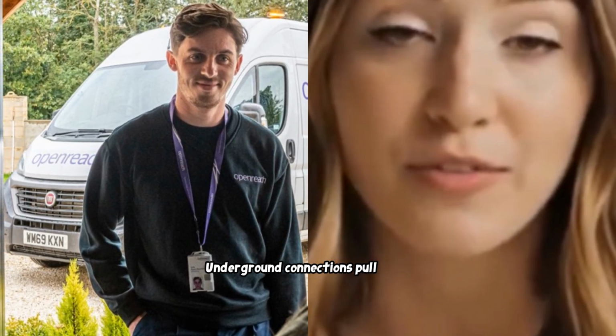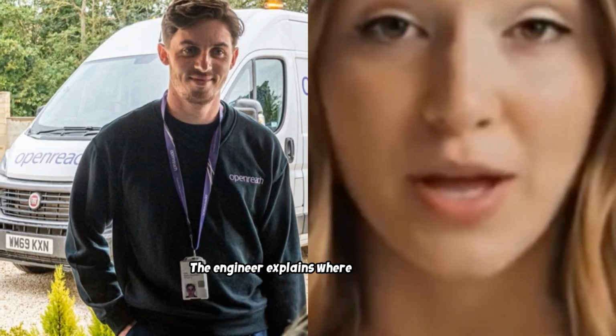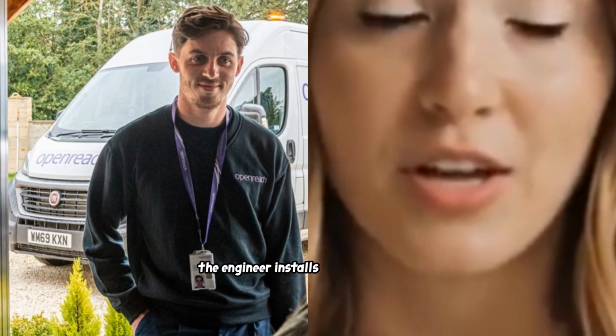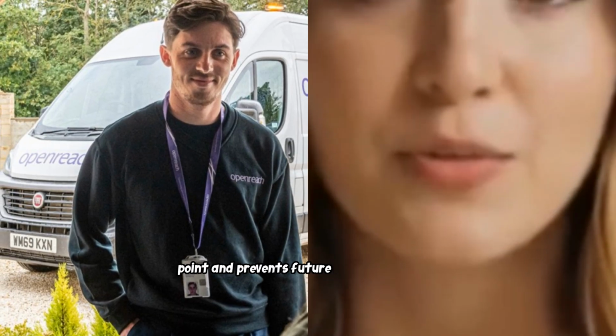Underground connections pull fiber through existing ducts. This may need a small amount of digging. It depends on where the duct is. The engineer explains where and why any digging is needed. Following the cable routing, the engineer installs a small external junction box on your outside wall. This box protects the fiber cable entry point and prevents future broadband issues.